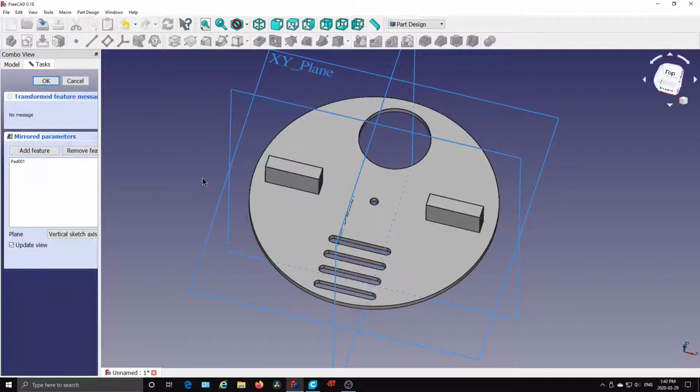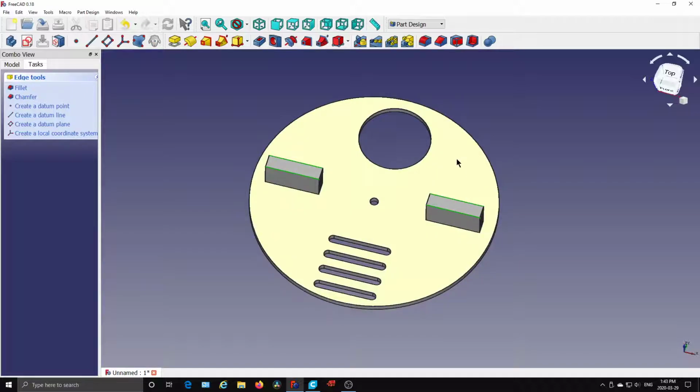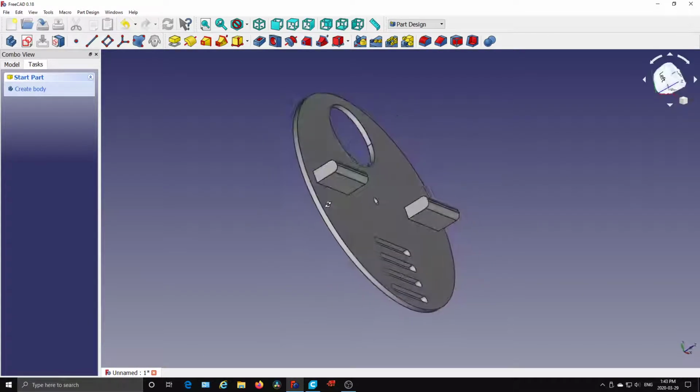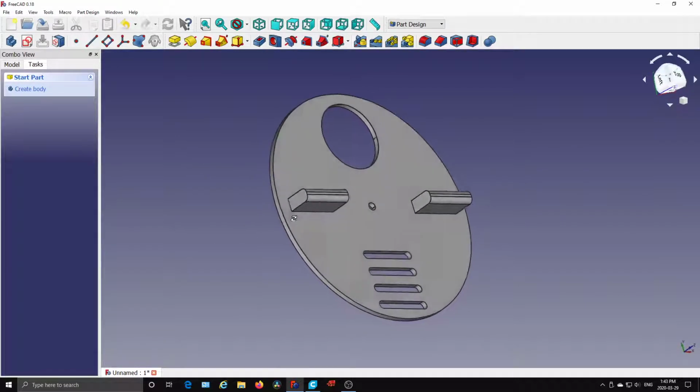Simple as that. And if you want, you can fancy these up a little bit by clicking that top edge, hold down the control key and selecting these other top edges and either putting a round fillet edge on it or a tapered chamfered edge. So you can put round on it and make it 2. Click OK. And there you have the nuke entrance. Simple as that.